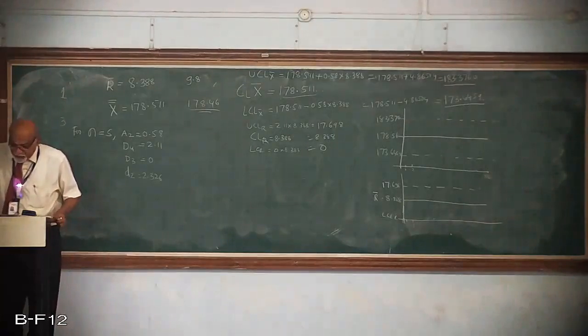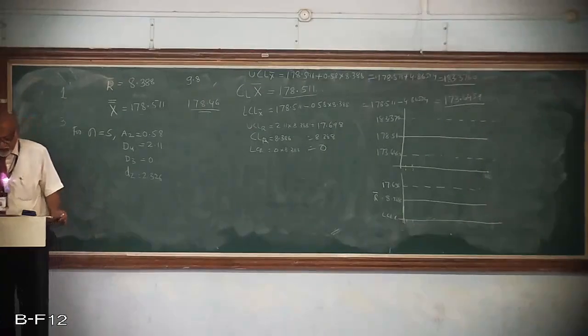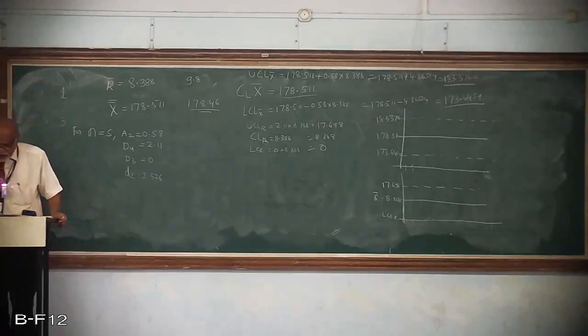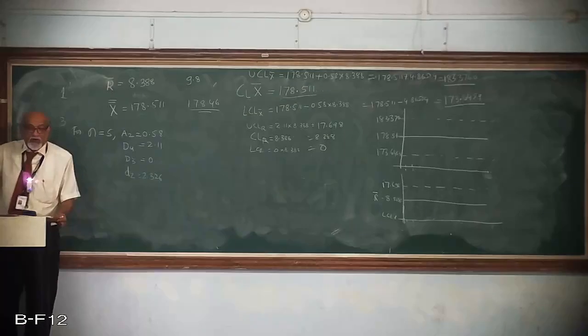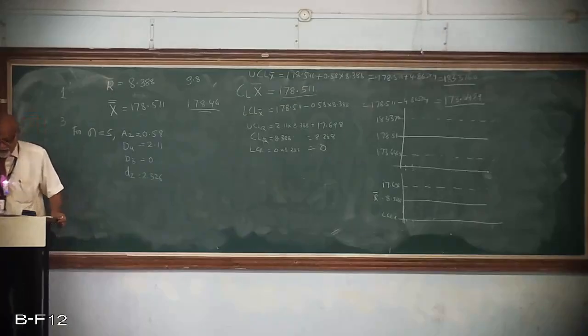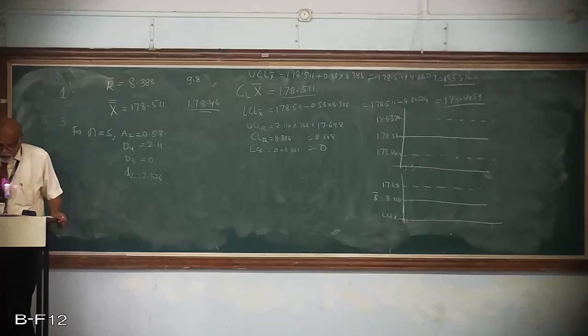If a product falls below lower specification limit of 160, it must be scrapped. Whereas if it falls above the upper specification limit of 182, it may be reworked, because scrapping an article is much more costly than the rework. It is desired to hold a scrap to a low figure without causing excessive rework. The process averages can be shifted by a relatively simple machine adjustment. What would you suggest as the aimed at value for process centering in the immediate future, and why?